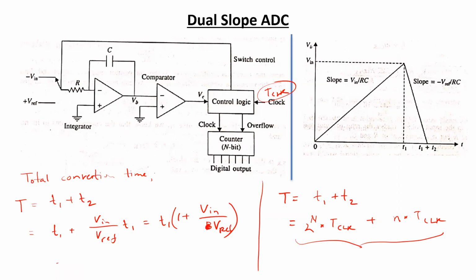Now both the single slope ADC and the dual slope ADC work on a principle that makes their conversion process a bit slower. So for applications which require faster response or faster conversion, such as data acquisition, signal conditioning or signal processing, the use of this type of ADC is not that useful.